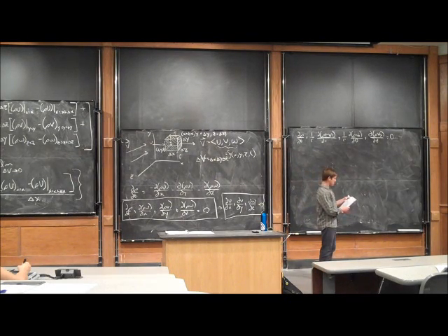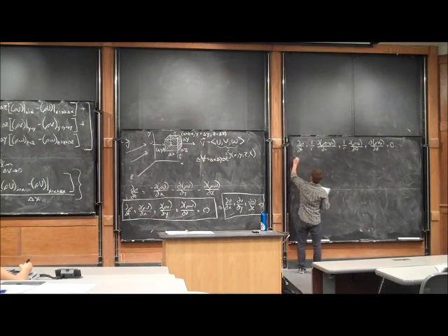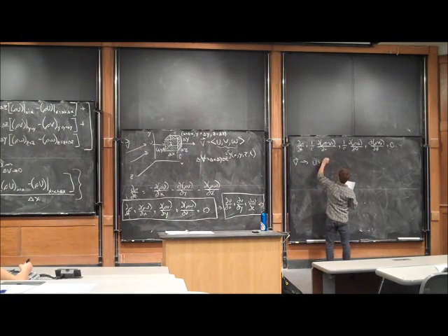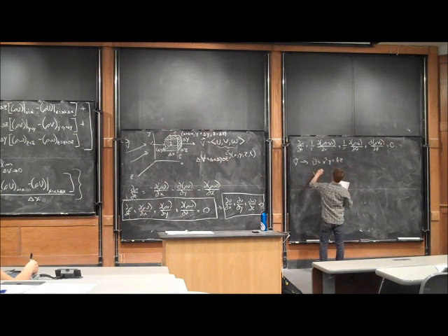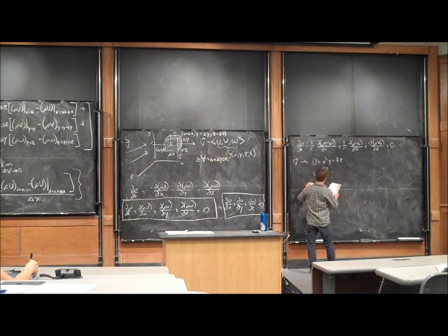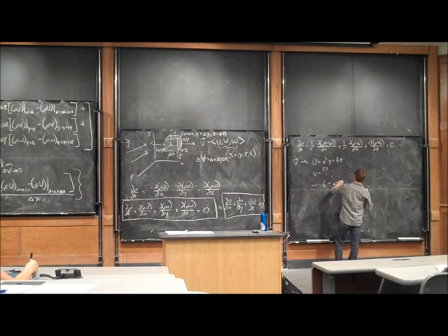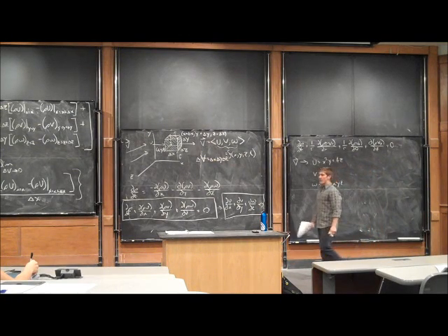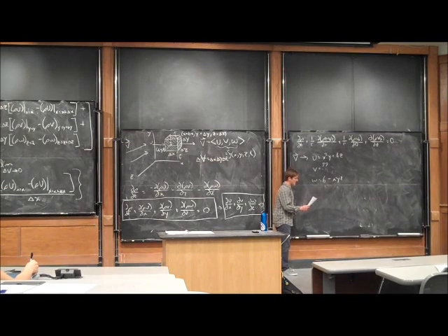Okay, so let's work an example. Let's say I have some velocity field given by u equal to x squared y plus 4z, v equal to something you don't know, and w equal to 6 minus xyz. We need to figure out what v is so this velocity field doesn't violate the conservation of mass. So that's what we're trying to do. We want to figure out what v has got to be.